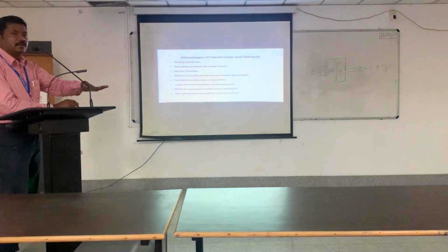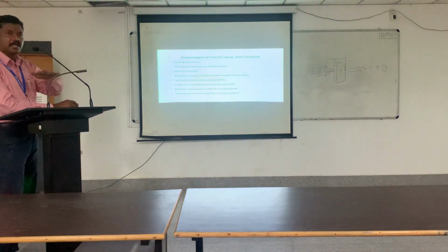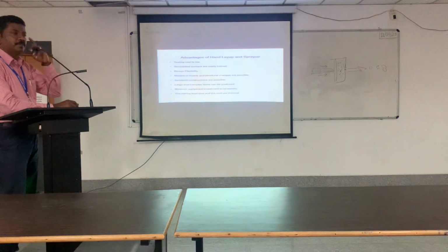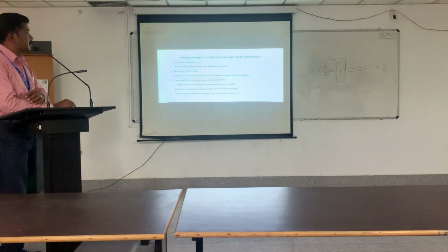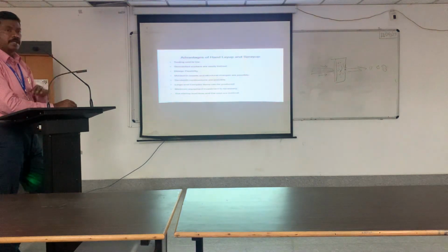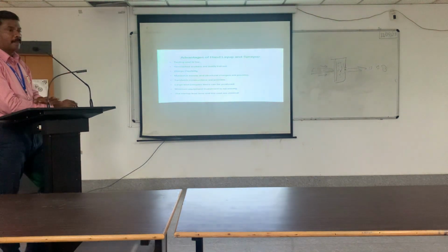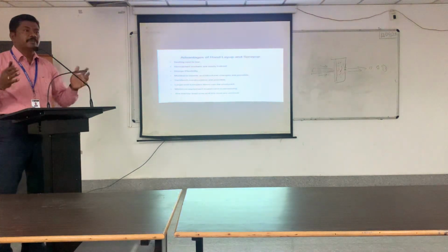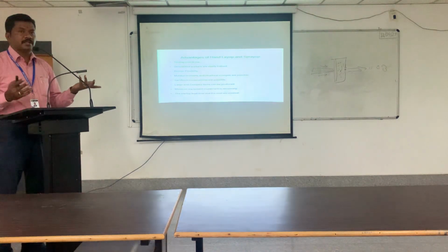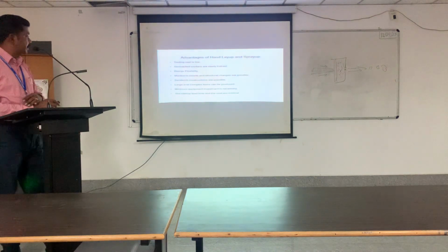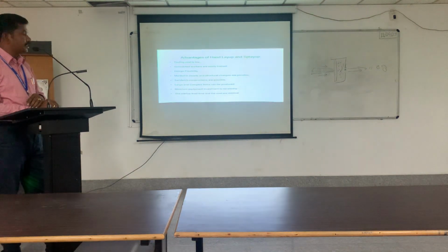In one layer you can use one fiber, in another layer you can use a steel rod, and in another layer you may want to use metal mesh, maybe aluminum mesh. Like this, sandwich constructions are possible. Large and complex items can be produced, with limited numbers. If you are going to produce large and complex items by compression molding, first you need to make the mold, isn't it? That is very costly. If it is mass production, you can make the mold. For job orders, this can be very easy. Minimum equipment investment is necessary. The startup, lead time and the cost are minimal.